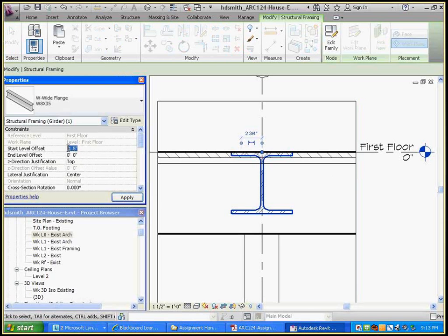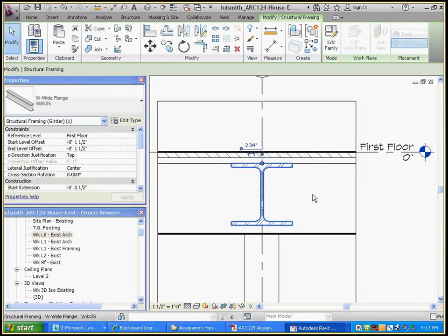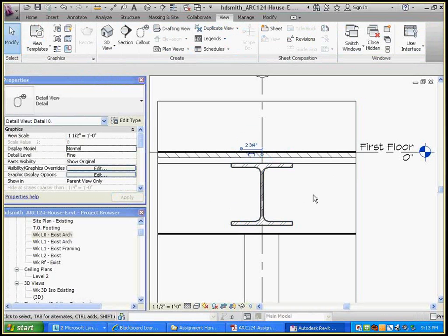The advantage again is that it hides the depth of the beam up in the floor structure so nobody bumps their head on it. The disadvantage is if I'm the guy building this, I've got to stop all these floor joists on either side, and I've got to put wood blocking in here bolted to the beam so I can put joist hangers on either side of that and hang those joists off the side.